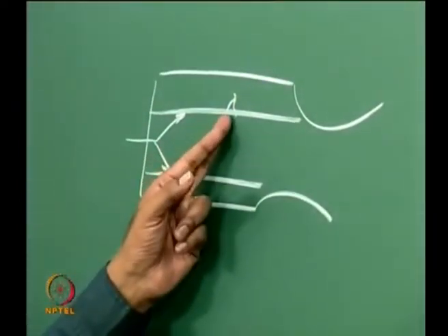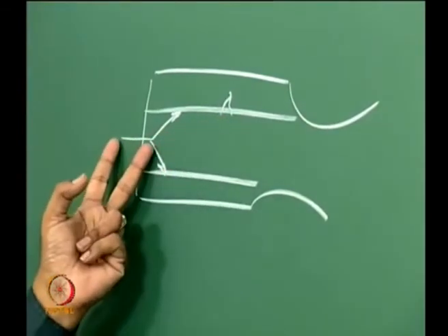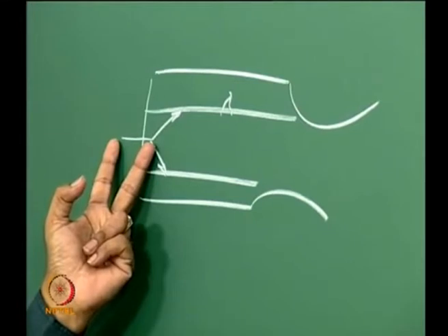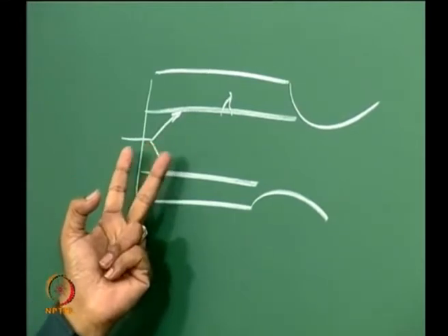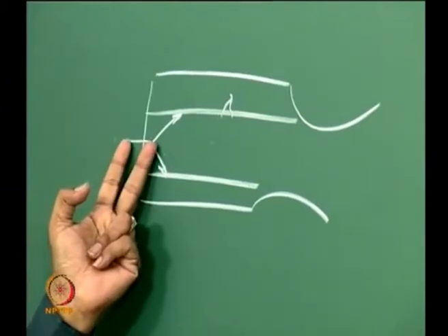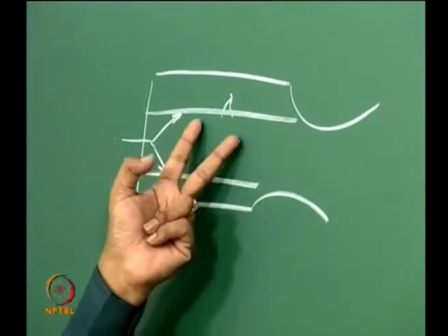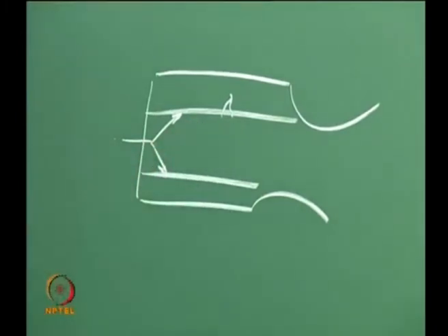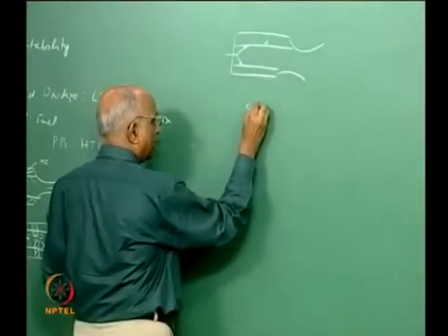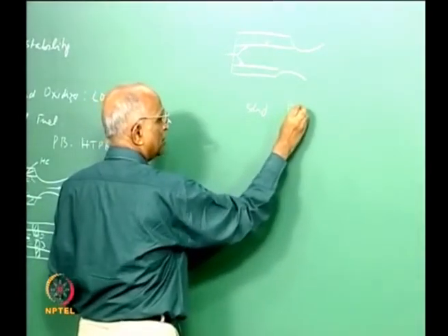Because the surface area is increasing, the pressure gets generated. When pressure gets generated, automatically the pressure drop across the injector decreases, because the pressure here is higher and this is constant pressure. The pressure drop decreases, and therefore the flow rate of oxidizer decreases, and therefore it is self-regulating. In other words, in solid propellant rockets, if there is a crack, its surface area increases, and pressure continues to increase.